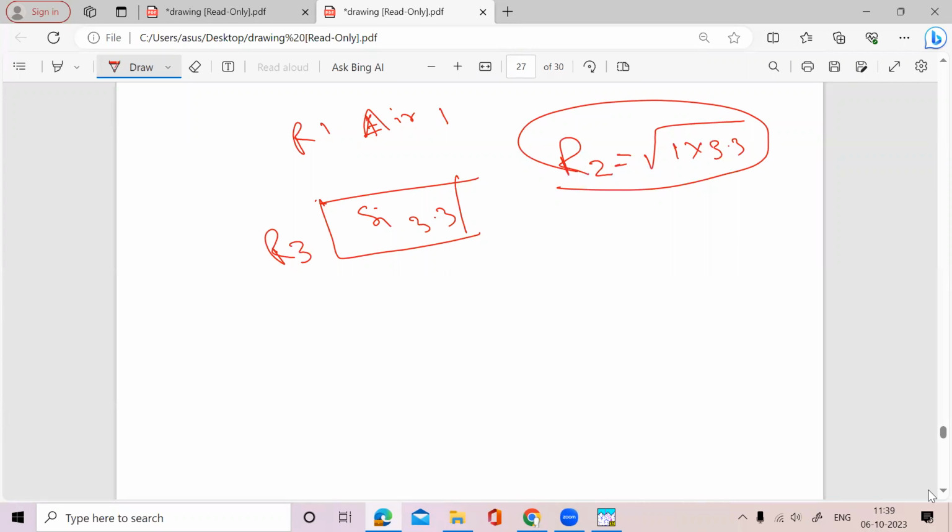Understood? Any problem? So I have to decide on this type of material only. Among these materials, apart from silicon nitride, there is silicon dioxide, aluminum oxide, zinc oxide, AZO, aluminum-doped zinc oxide, and silicon oxynitride. So many things are there, but the most popular is still silicon nitride. Why? I will tell later. But now aluminum oxide is also very popular in industry, because their refractive index lies in between these two values. So this is one problem solved, the refractive index.